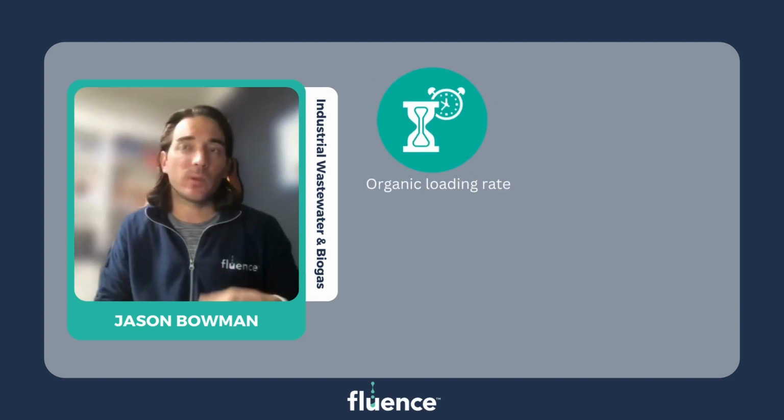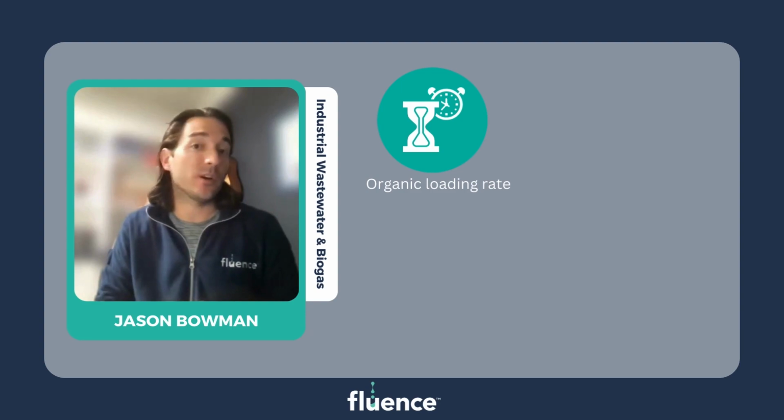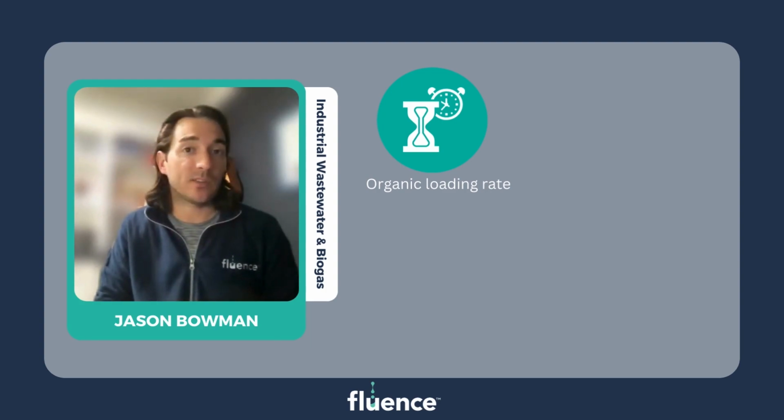So this is the relative organic mass to digester volume ratio. It basically says how much organic you have coming in versus how much volume we need to reduce or remove that organic load. So this is going to vary based on the biodegradability and based on the style of digester, and we'll talk about that more in a minute.